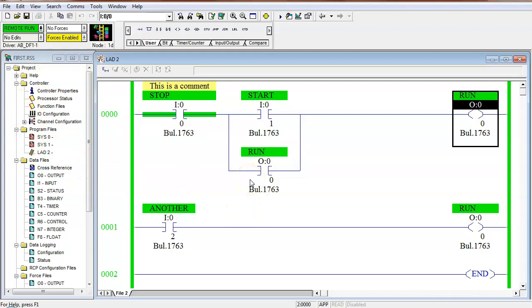That's one question right there. We got another add right there. I just gave it a name I wanted to give. Symbols are yours. And what you want to do though is you want to give it a name that gives you some idea of what it does in the program. So this stop and start is obvious. When we come over here, I'll show y'all the Allen Bradley diagrams, ladder logic for the Festo line down there, and you'll see every one of those symbols gives you an idea of what that thing does in that program. And if you want to clarify it more, you give it a comment.